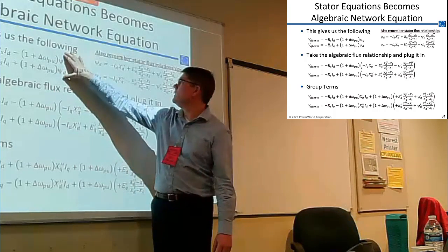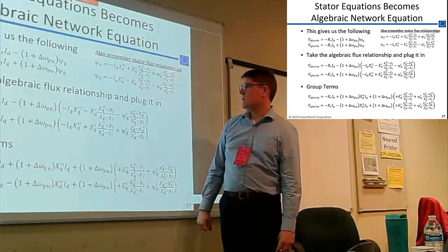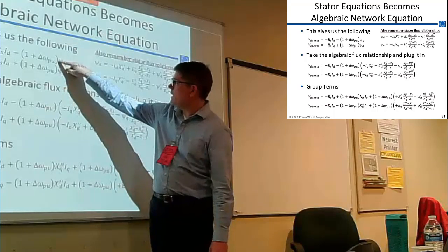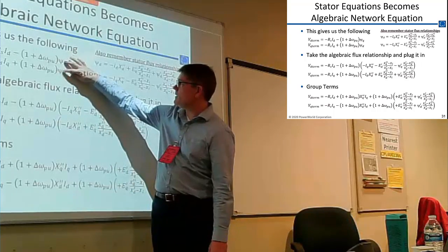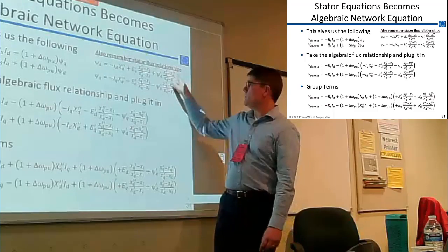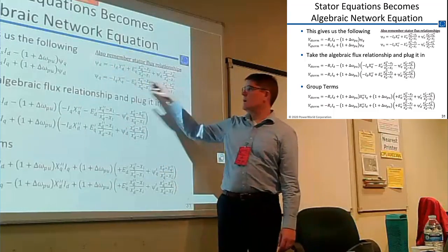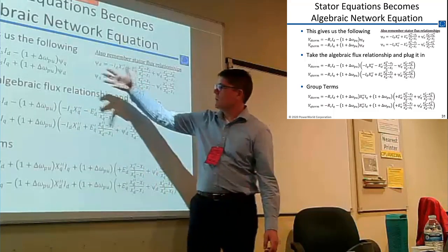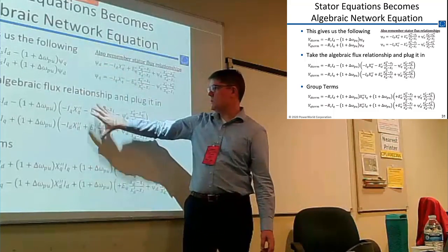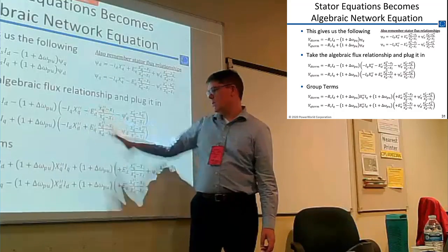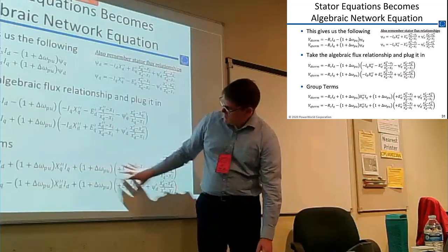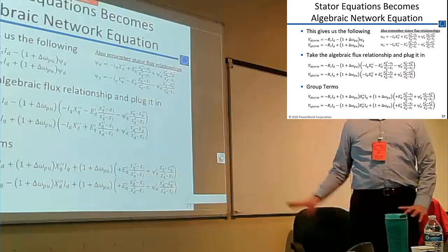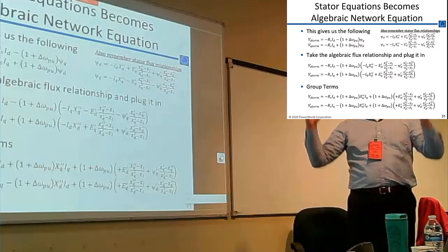If you multiply these out, so now I have flux. These are the stator fluxes, but remember there was also a bunch of algebra here that said the relationship between the stator and the rotor fluxes is this. So then you take these and substitute them down here, you group terms together, and then we get these equations down here. And eventually I'm going to get to the end here, and I'll pull up the round rotor block diagram and say, okay, this is where all this stuff came from. So trust me.